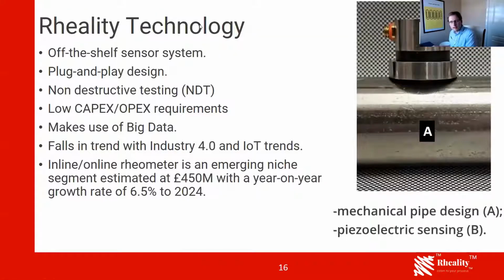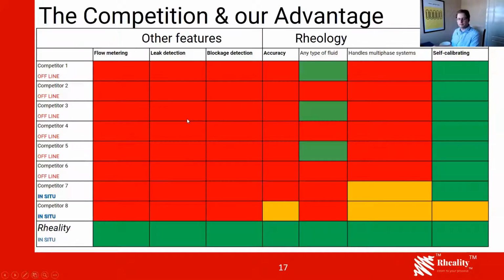And what happens is that the fluid enters the pipe segment. There is a T-shaped intrusion of a specific mechanical design. What happens is we perturb the flow in a very controlled manner when it passes that pin, and we force the fluid to release transient energy, and that energy would basically be conveyed through the pin to the sensor's sensitive area, and then we would process it with our detection equipment.